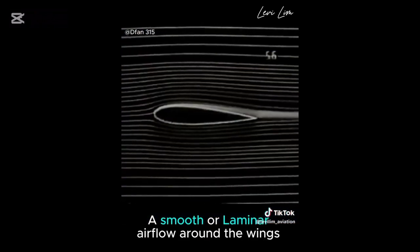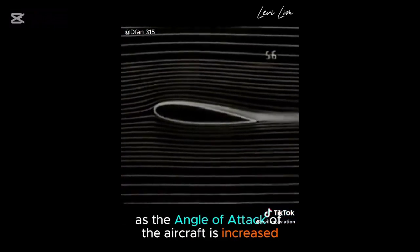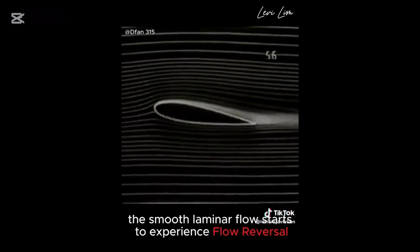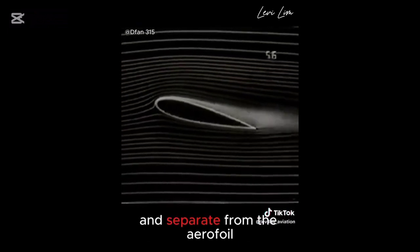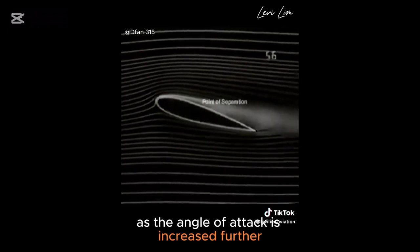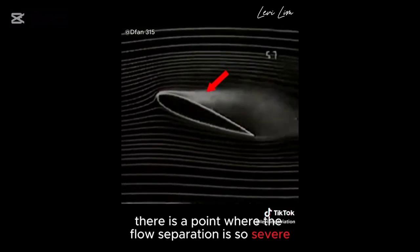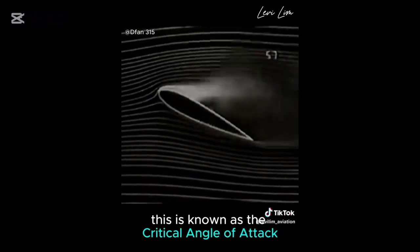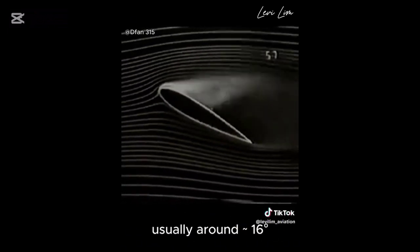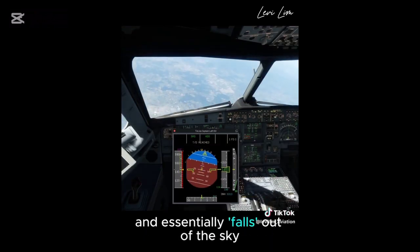A smooth or laminar airflow around the wings is required for stable lift generation. As the angle of attack of the aircraft is increased, the smooth laminar flow starts to experience flow reversal. This causes the airflow to turn turbulent and separate from the aerofoil. As the angle of attack is increased further, the point of separation moves forward. There is a point where the flow separation is so severe that lift generation is no longer sufficient for level flight. This is known as the critical angle of attack, usually around 16 degrees. The aircraft stalls and essentially falls out of the sky.